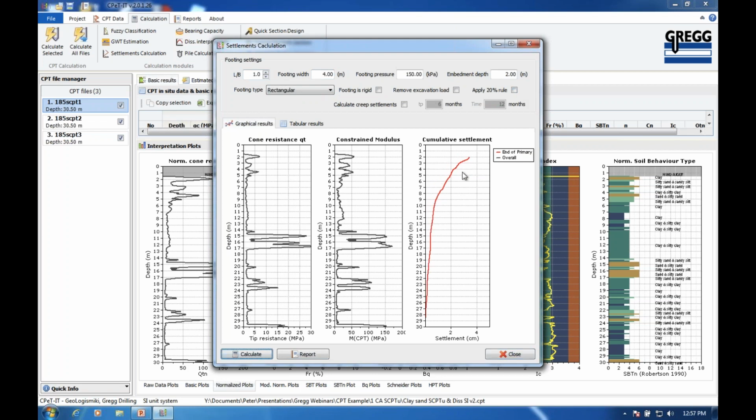I can remove that and it'll calculate it all the way down. And so you can see it didn't change the result a little bit, it's just picking up a little bit of settlement in the lower clay. But you can see most of the settlements in the upper clay because after all it's a 4 meter strip footing. If I made it 10 meters, like an embankment, obviously the numbers will change. It got quite a bit bigger. Let's go back to 4.